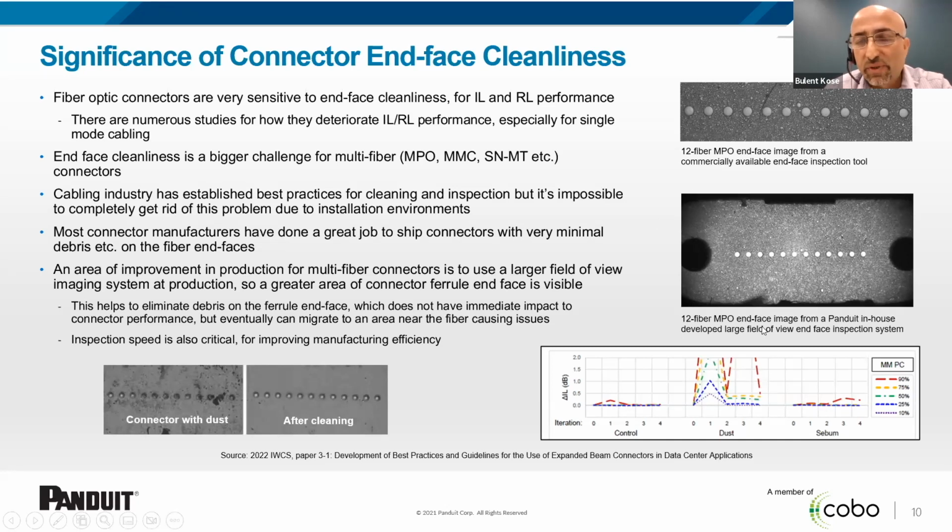The reason for this is, in case there is some debris or dust in an area where the imaging system couldn't see, and then this was shipped, that dust or debris can travel to the middle of the connector and contaminate the fibers. So this would be a good way to improve the end-face cleanliness in production.